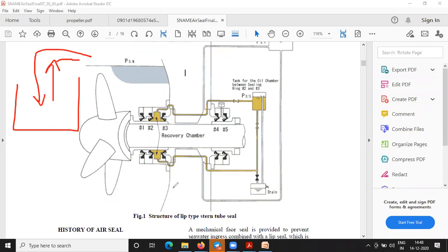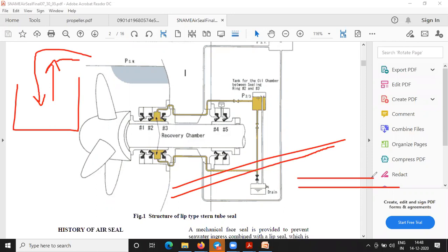That is why your boiler tubes are slightly slant. No boiler you will find directly horizontal. All the boiler tubes are slightly slant. Why? That is one of the things. The water is self-circulating. The hot water will rise up, cold water will fall down. Same thing here.